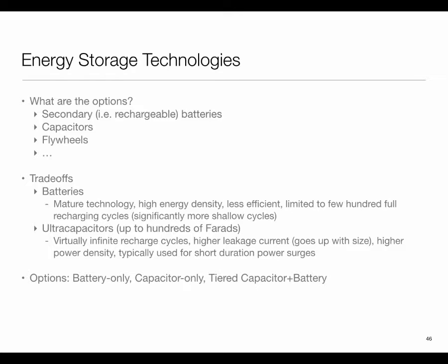Thermal gradient, hot cold difference. So you can exploit that. You can get it from organic material, literally the way the human body takes energy out of food, so involving biological processes. One of the very common ones now, as I mentioned earlier, is radio waves. In fact, some groups have shown that they can scavenge enough energy from the TV signals which are already around us, or even Wi-Fi signals.